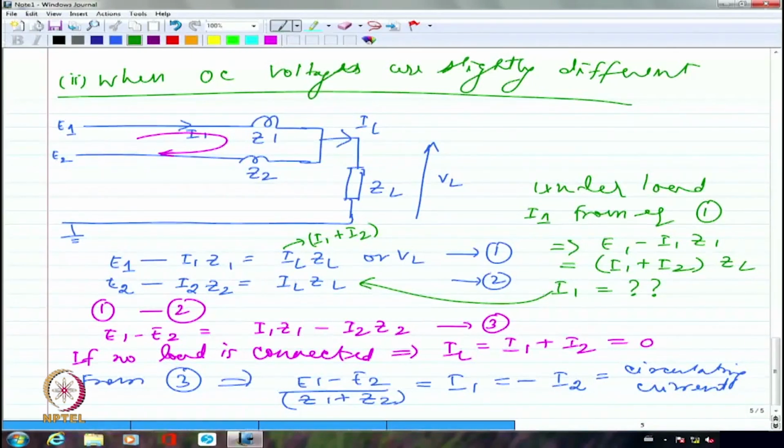So, parallel operation of transformers is possible whenever the voltage ratios are equal. But even if they are of different capacity, I can definitely operate a 100 kVA transformer in parallel with a 50 kVA transformer. No problem. Only thing is, if I am sharing a load of 120 kVA, I would like the 100 kVA to take 80 and I would like the other transformer, 50 kVA, to take 40.